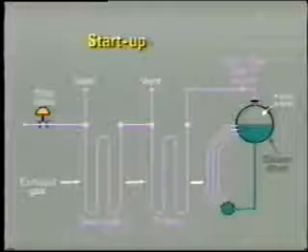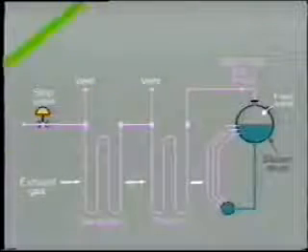The vertical superheater shown here is known as the pendant type because it is supported by and hangs freely from the inlet and outlet headers. This allows the superheater great flexibility in accommodating expansion, particularly during startup or rapid load changes. During startup, the headers must be vented to atmosphere. This is to allow any accumulated condensate to boil off during the startup and so allow free flow of steam through the superheater tubes. But why is this necessary?